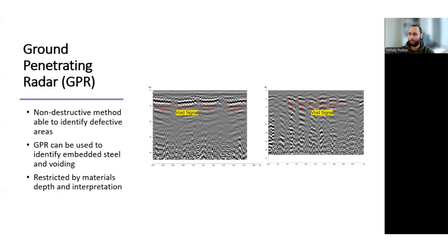These devices are useful for all concrete elements as they come in many different sizes as well, so one can choose the best size for the job. The one major downside to them is the limited penetration depth, and this combined with the inability to see through metallic objects makes them a little inefficient in scanning densely reinforced and thick concrete elements.